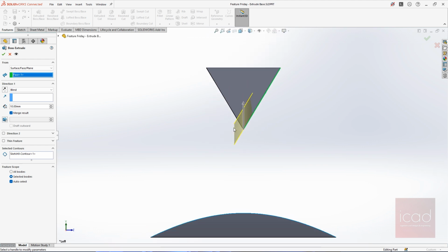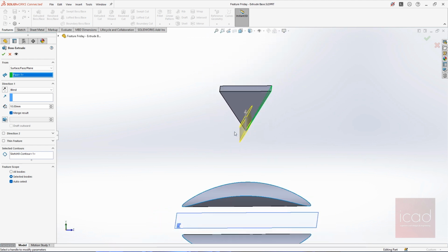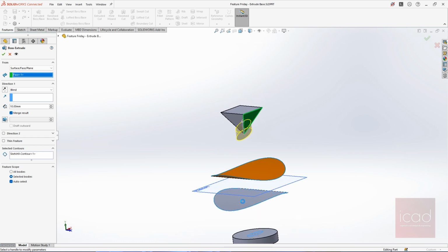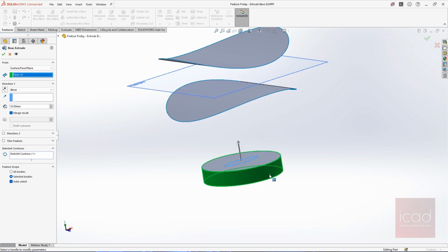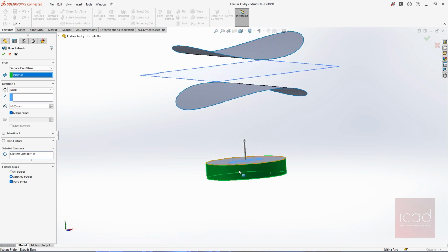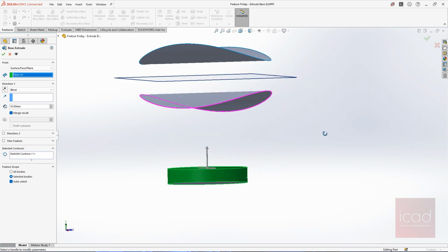It's totally different, and it's nothing similar to the one we saw earlier. I can select this face, it doesn't matter what face, but I cannot select this face because the face that I've selected is perpendicular to the sketch. So there is no way my sketch can project onto this particular face. That's why I cannot select the faces or planes which are perpendicular to my sketch, right?